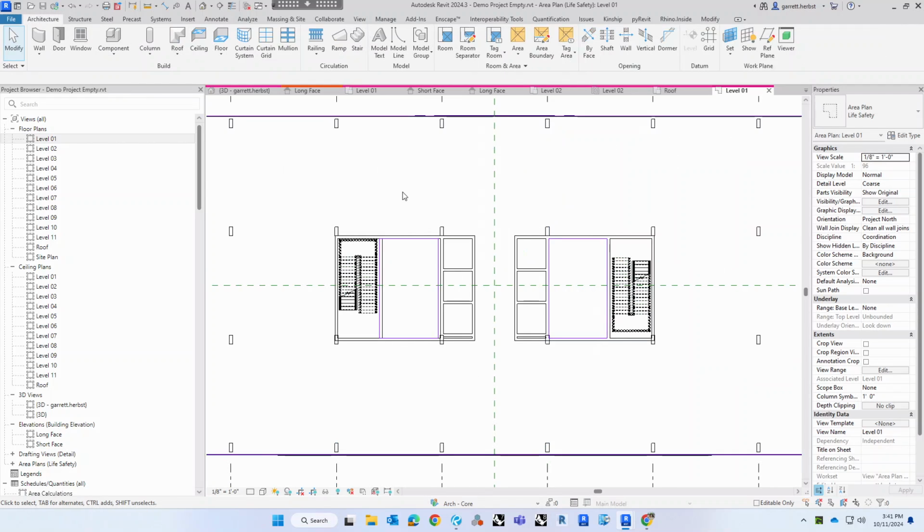There are also very strict rules on where you can put the location lines at the exterior. For solid walls, it goes to the back face of the wall. With drywall, it would go to the back face of the drywall. But with glazing, it actually goes to the back face of the glass. So it goes in and out and all this stuff. In any case, once you draw those area boundaries,